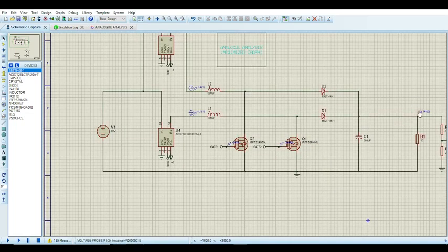I'm talking about the output here. If you're just controlling only the voltage directly, and you're not controlling the current, then the current going through your inductor is going to be kind of crazy, because you're not taking it into account. It's going to affect your MOSFETs in the long run, and that's the issue.